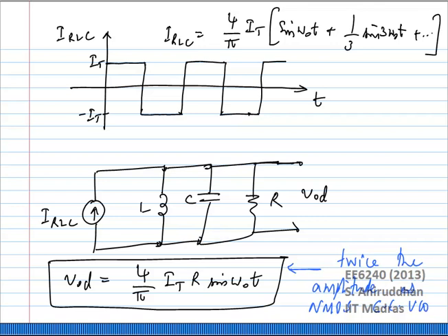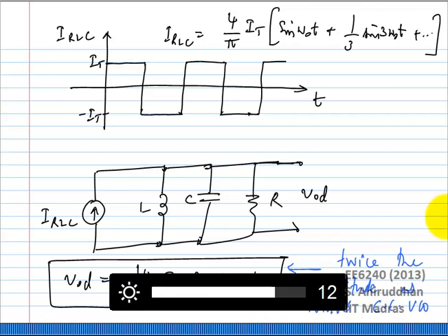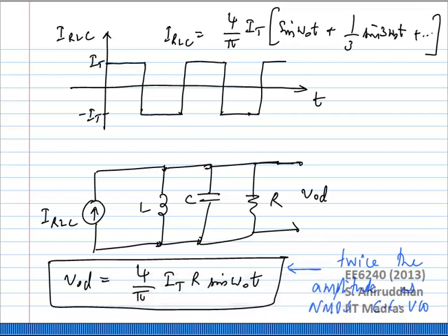Right? So let us say for linearity concerns, you wanted a 1 volt sinusoid at the LO port. If this was 1.001, do you think anything will happen to the operation of the mixer? Of course not. It will look exactly the same as before. Right? It will not look any different at all. Linearity will also be practically the same.